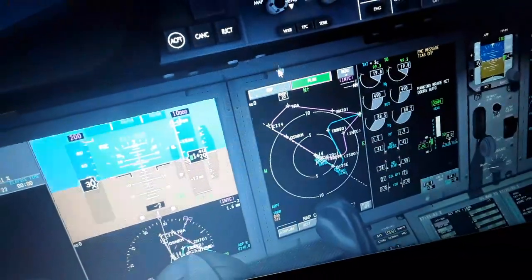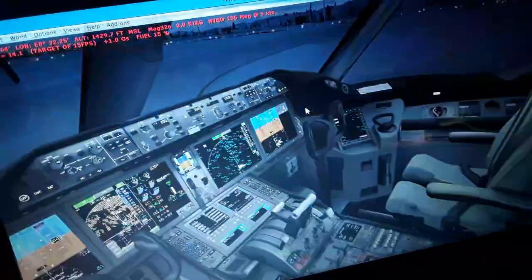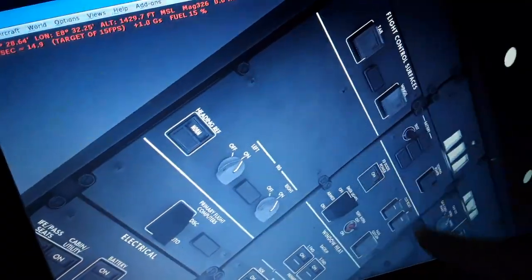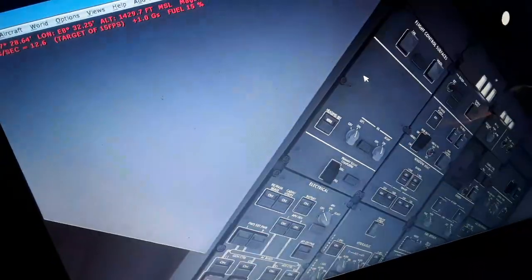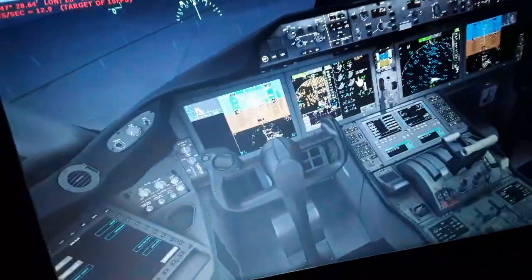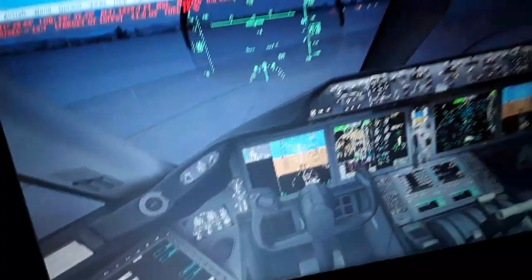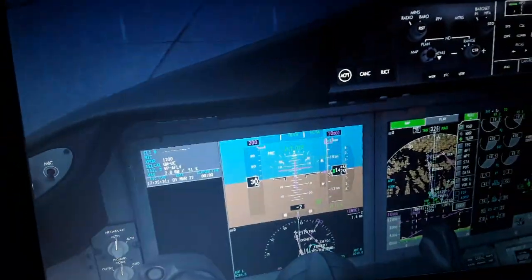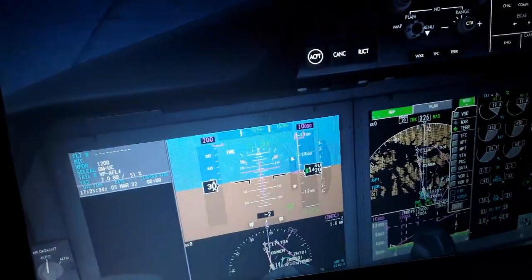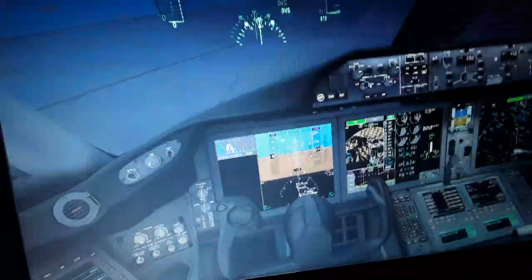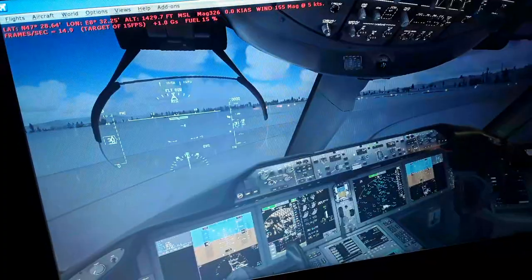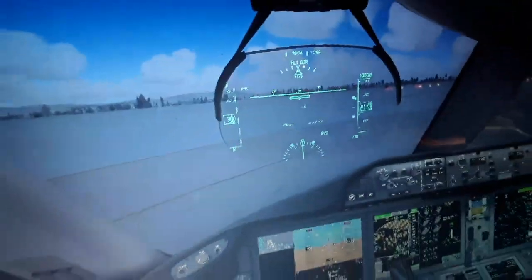So all the data you see here, all the air data, we have the air data computer here that also has GPS receivers, magnetic heading, geographic North Pole, inertial reference alignment, laser gyroscope, laser alignment, also pitot static and dynamic pitot tubes for the airspeed and the barometric altitude, the vertical rate of climb and descent, the angle of attack, radio altitude above ground level, GPS receivers, terrain map. So you see everything here, all the data are displayed from the data computer.